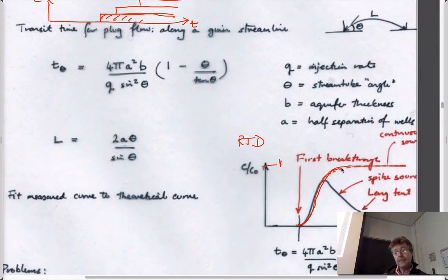And so even in the case that your longitudinal dispersion is 0, right, plug flow, absolutely no dispersion, your experiment tells you that it has some. And it tells you it has some because the experiment itself introduces this kind of dispersive flow field. And so it's not very useful to do that.